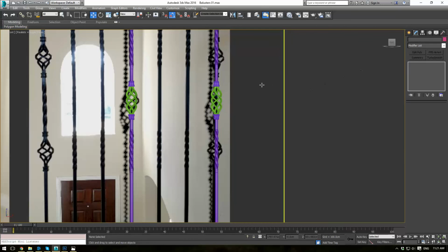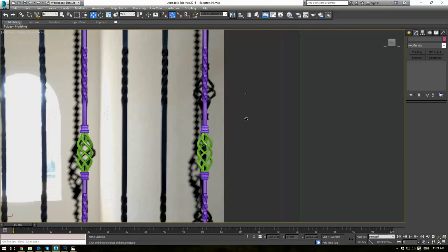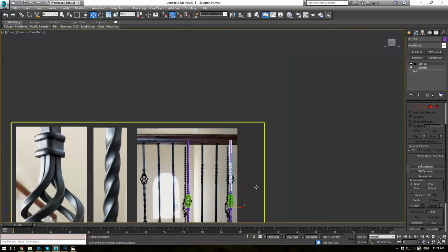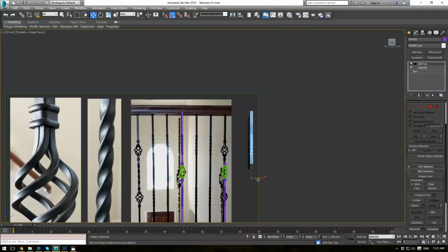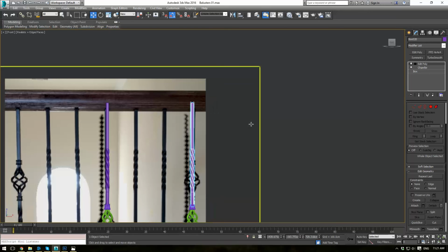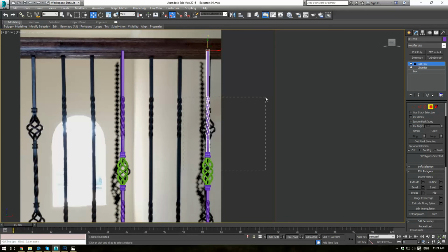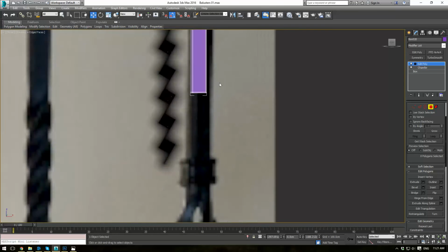Okay. And let's first see what we've got here. So this guy looks like it's just a standard piece. So let's go to our edit poly and delete all of the unnecessary twists here.